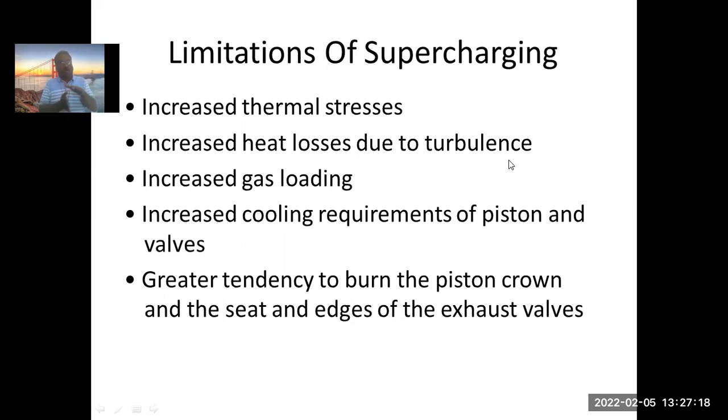Now we are going for supercharging. Supercharging means increasing the pressure. Increasing the pressure means in the same volume, we now accommodate more molecules. So the number of collisions is going to increase, and that will result in an increase in temperature, correct? So we are getting higher temperature along with higher turbulence.